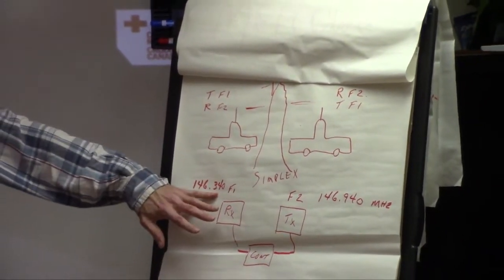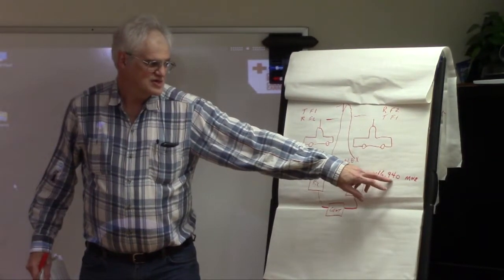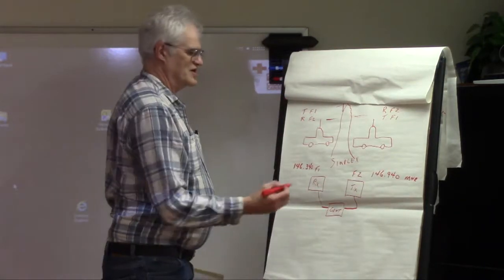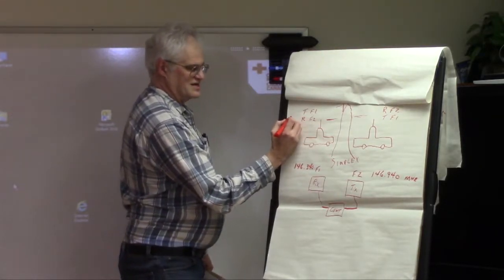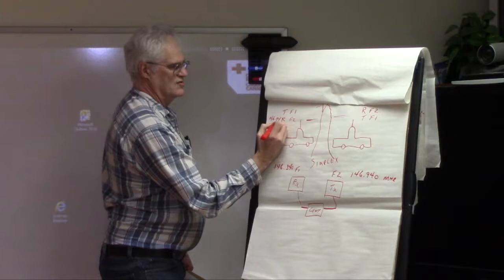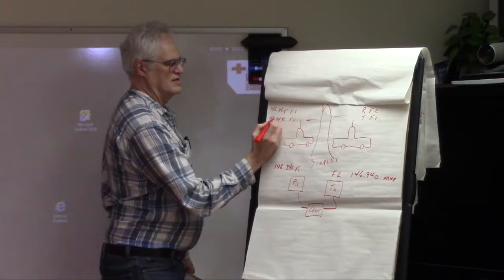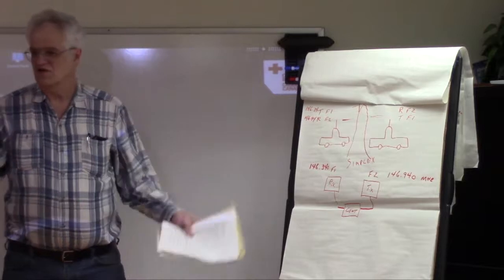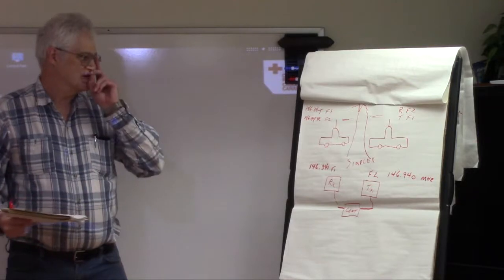It listens on a frequency of 146.34, transmits on a frequency of 146.94. But likewise, your vehicles are going to be reversed, so your mobile has got to listen. So your transmit frequency in your radios, your mobiles, your portables, are actually going to be opposite to what the repeater is.